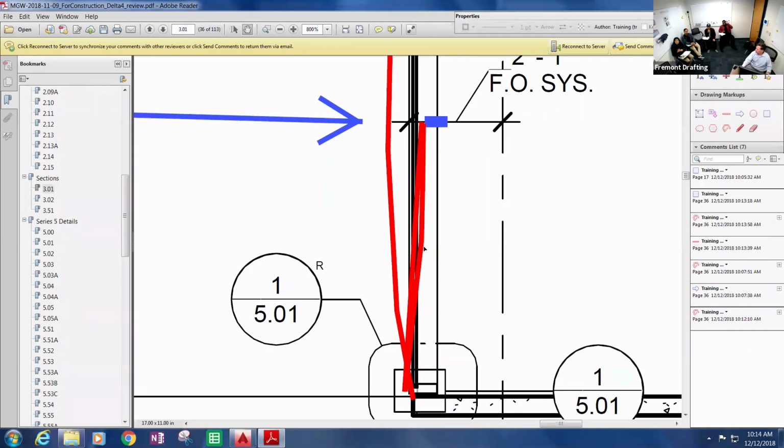So you're measuring at the worst case, imagining that the mullion is deflected also. Yes. Okay. Because if the glass deflects, the mullion is deflecting too. I'm not going to have the glass deflect on its own. Yeah, they're not totally moving independent of each other.